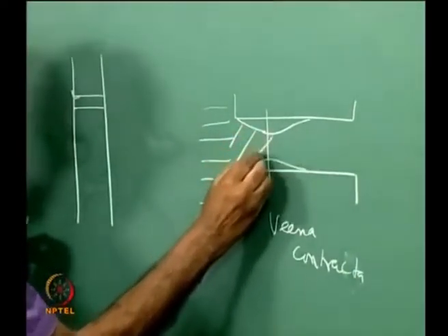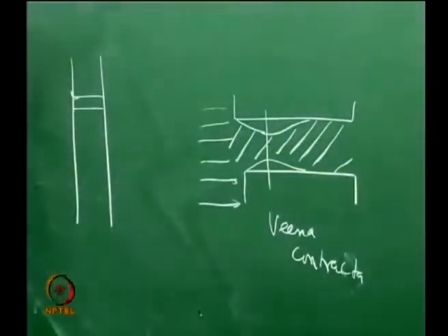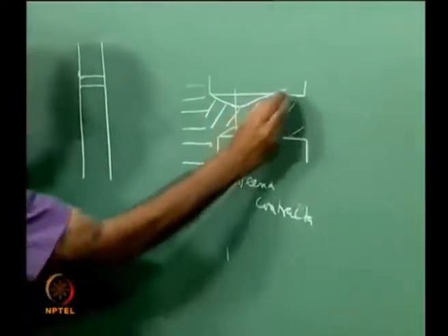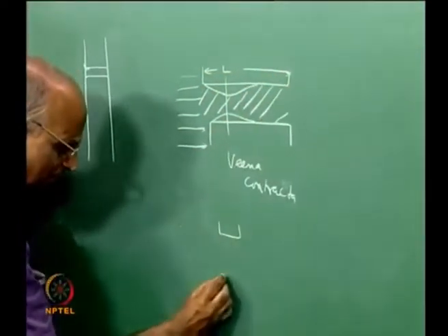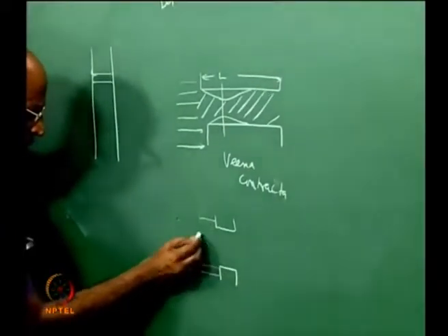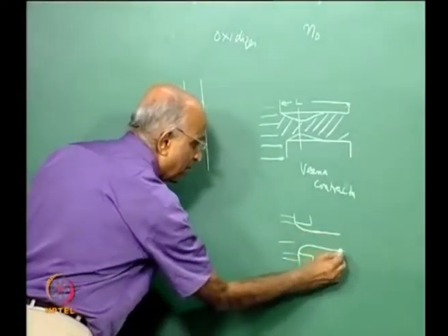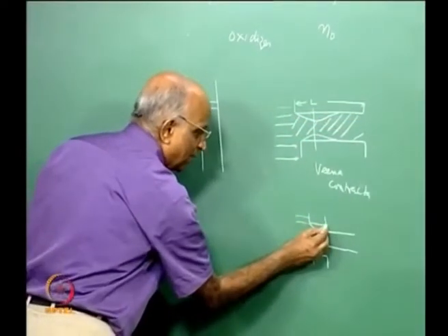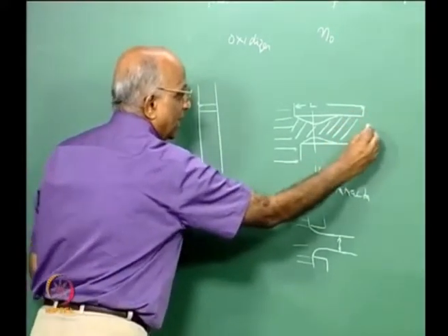In other words, this is the way the liquid is flowing. If I have my shower head, which has a very small dimension, that means instead of having such a length of the orifice, my length is something like this and it is again sharp edged. The flow is coming over here and the flow now contracts and goes like this, straight. That means the flow does not reattach back to the wall, in fact the flow is going like this, and therefore the area of flow is going to be much lower than the area of the orifices.